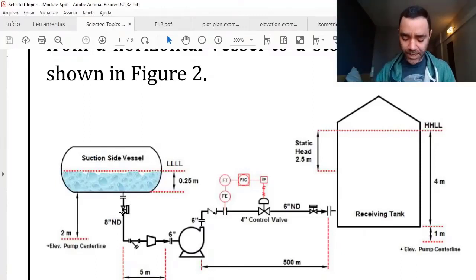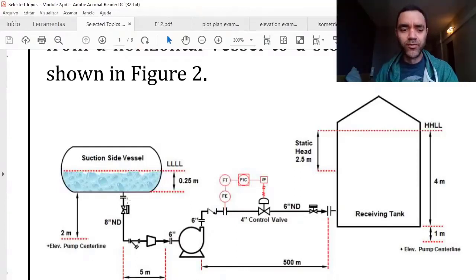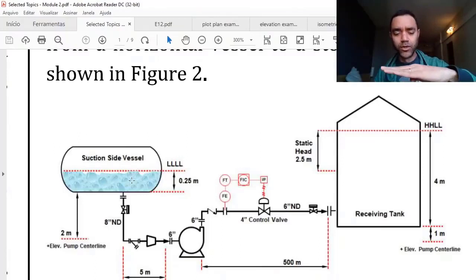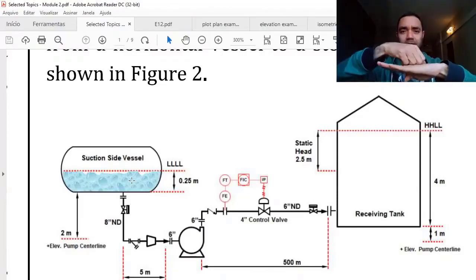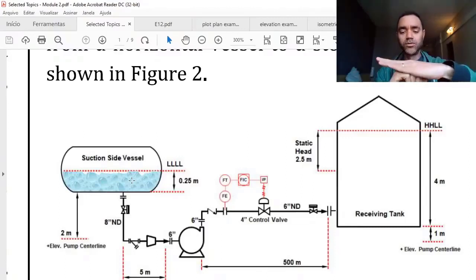During commissioning and startup, usually we fill the tanks or the vessels with the isolation valve closed. Now imagine if we have 2 tons of water in your tank, how will you be able to turn the manual valve? Because there will be much pressure on one side and almost no pressure on the other side.